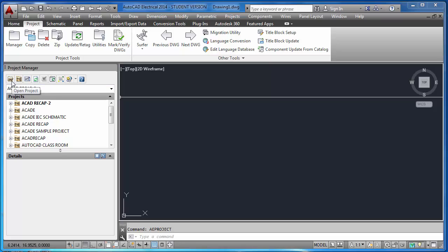I am going to make a new project. This is the new project tab. This is open project. If you already have a project, you can open it from here, but I don't have it right now. I have, but let us assume we don't. This is for new project, and this is new drawing, refresh, project wide utilities, and drawing list display, how we want to display the drawings inside this Project Manager, and plot, publish, and all. So let us start with a new project. I don't have an existing project open, so I am going straight to the new project.